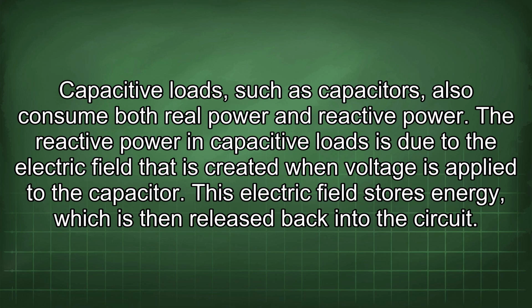Capacitive loads, such as capacitors, also consume both real power and reactive power. The reactive power in capacitive loads is due to the electric field that is created when voltage is applied to the capacitor. This electric field stores energy, which is then released back into the circuit.